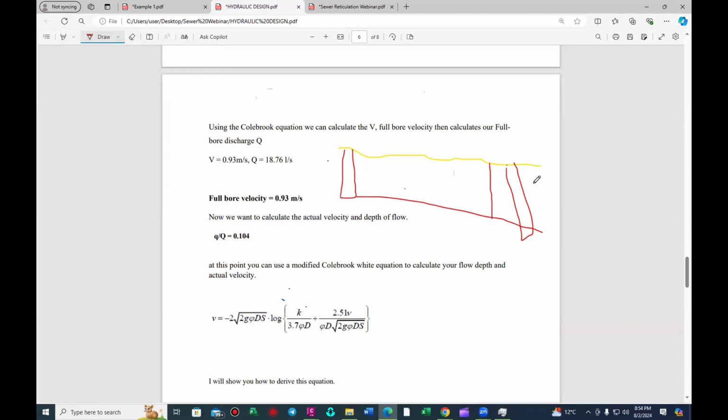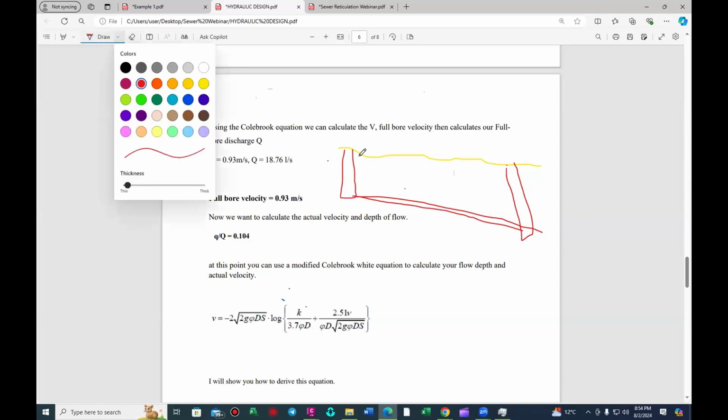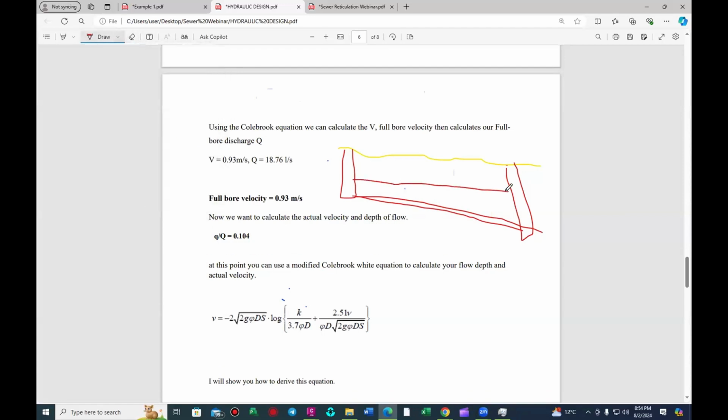If you want to know how deep 2.5 meters or 2 meters is, just look at the door in your room. That's 2 meters right there. So imagine us digging that 2 meters for a pipeline, let's say 56 kilometers. That's a lot of money. So if your pipe is too steep, your trench depth will be very deep. But if it's too flat, it's going to compromise your cleansing velocity. So if it's too flat, then your cleansing velocity will what?